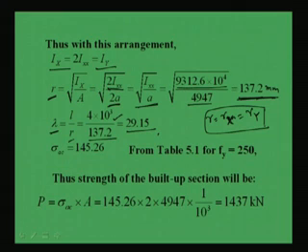So, now from this slenderness ratio value, and for Fy equal to 250, if we assume the steel grade as 250, then from table 5.1 of IS 800, what will we get? We will get sigma AC, the permissible compressive stress in the member.